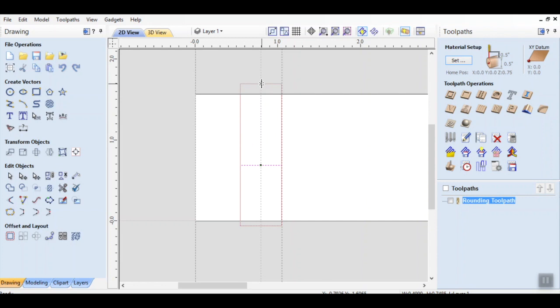The reason I go past this is if you don't go past it, it comes up to that edge and leaves a little dimple right there where the tooling starts. Because the edge of the tooling will go there and stop, so that'll leave a little material left on either side. The other problem that I just thought of, let's go back to our square.